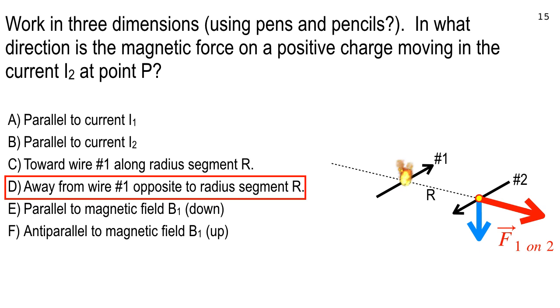Now, field point number 2, let's burn it in there. Field point J. Field point P we got squared away. Now, what's going to happen here? We've got current going this way, but what direction is the magnetic field from number 2?